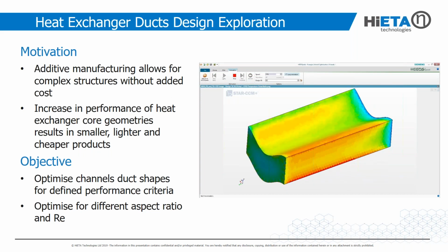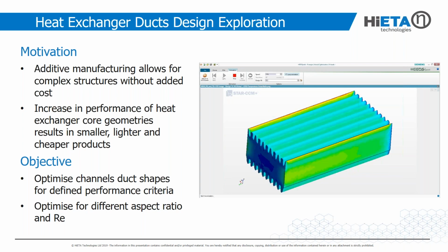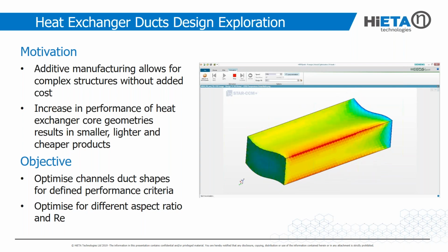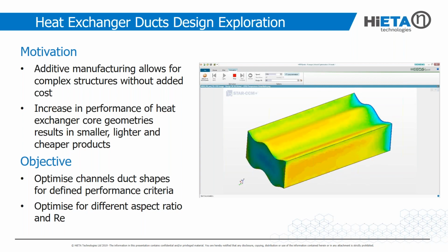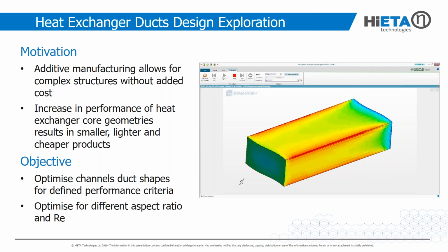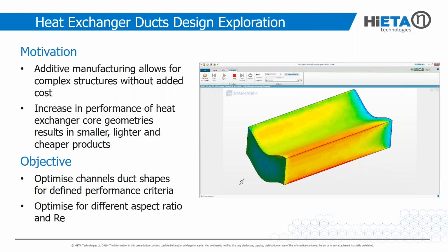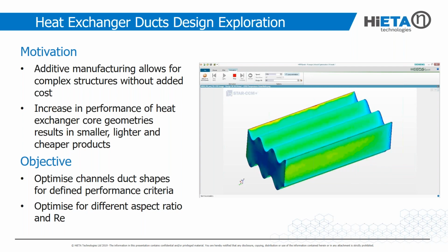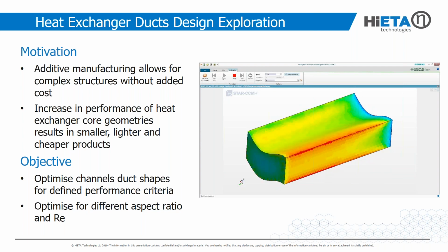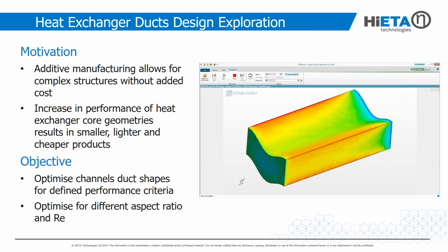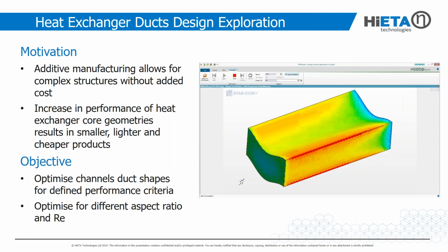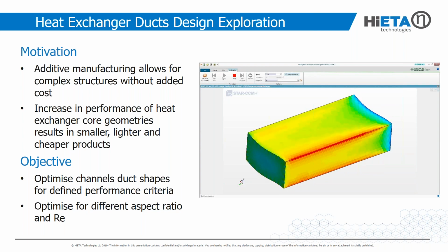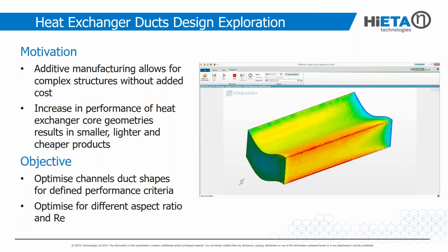What was the motivation here? The motivation was, as I mentioned, that we usually did an iterative process to get our best heat transfer surfaces, using iterations and engineering best judgment. What we did here was use HEEDS to combine Star-CCM+ with a CAD modeler. You can use any CAD modeler, like SolidWorks as well, and combine them, and then you give your cost functions, what you are trying to achieve.